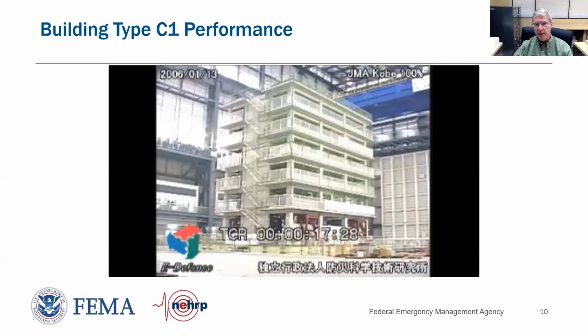And we're going to see how that panel, that concrete architectural panel in between the columns, is one of our classic vertical irregularities that we capture in the P-154 procedure. And that is we have a short column effect. And so that's one of our vertical irregularities that we look for. So this is modeling that. The columns, by the way, are non-ductile. So they constructed it with steel such that they have a non-ductile concrete frame, older concrete buildings.